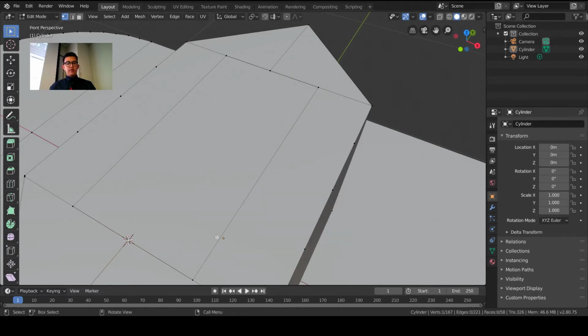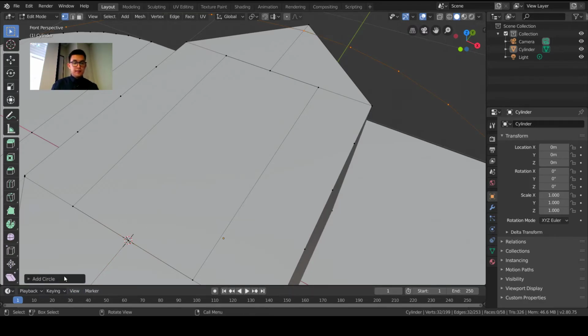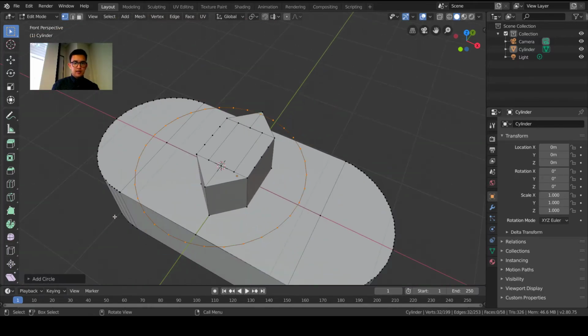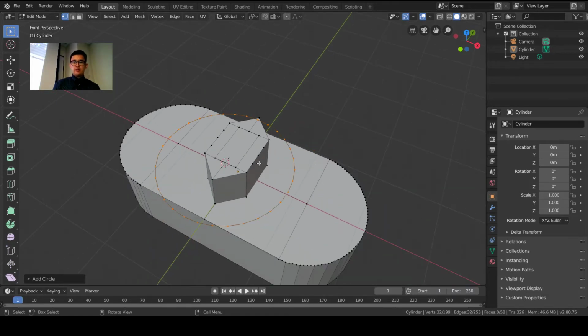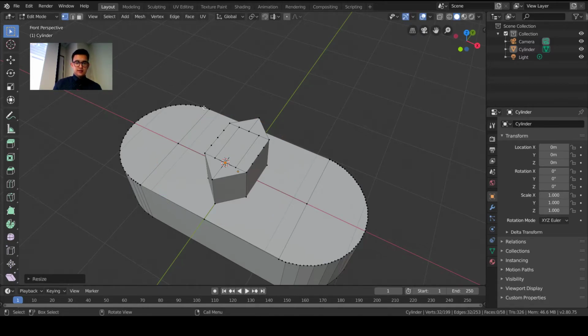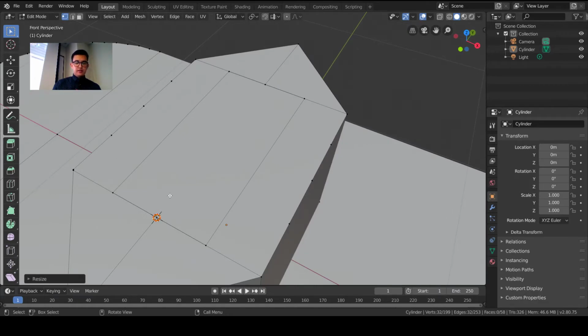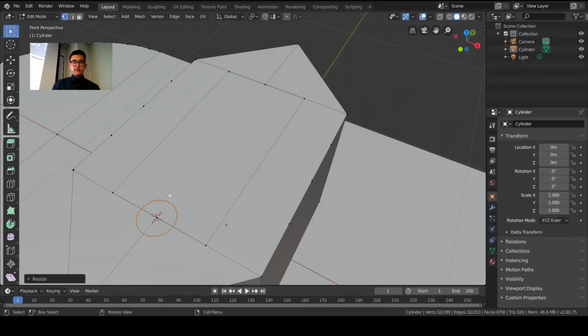And so now when I press Shift A and make a circle, it will be rendered about this 3D cursor point. So right now it's kind of big, but I can press S for scale and type 0.01 to make it 1/100th of the size. Maybe that's too small, so I'll press S again and then scale it by 3, maybe 4 or 5. You can kind of play around. So let's make it 5 times bigger, and there's a circle there.